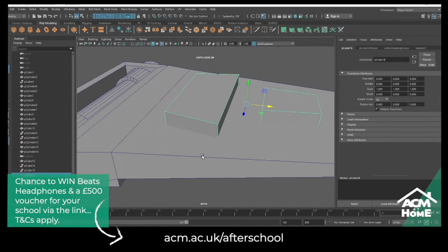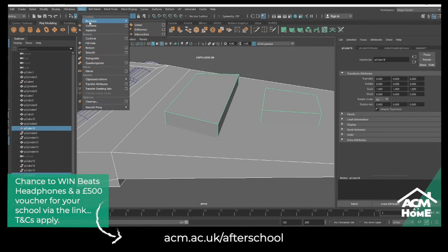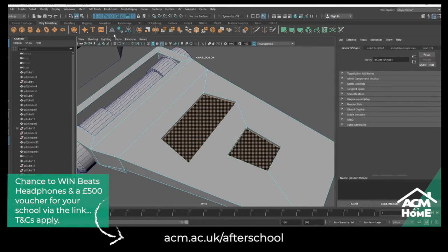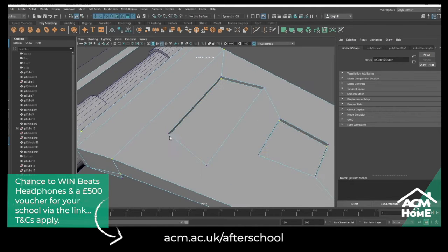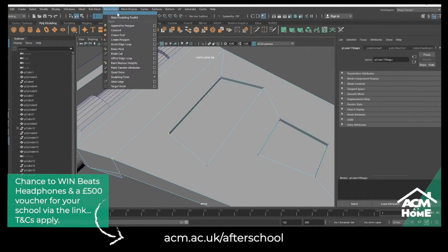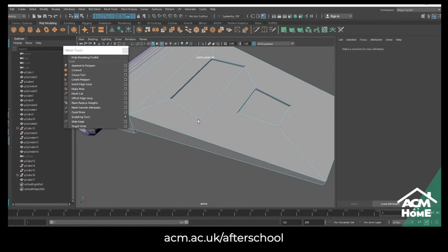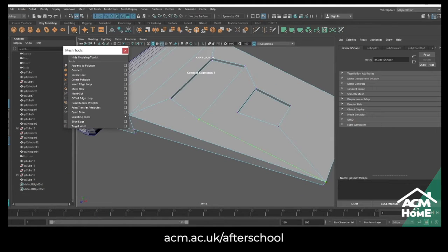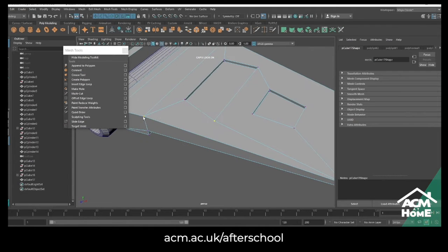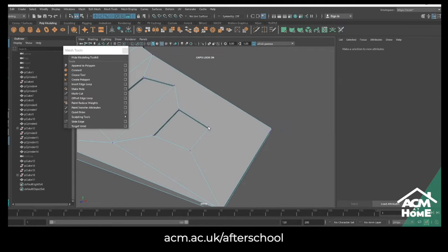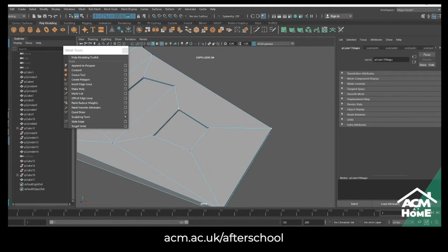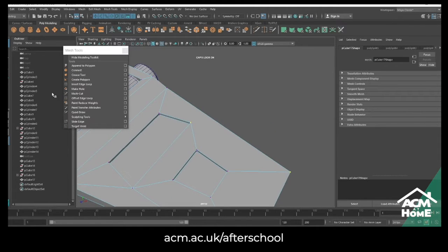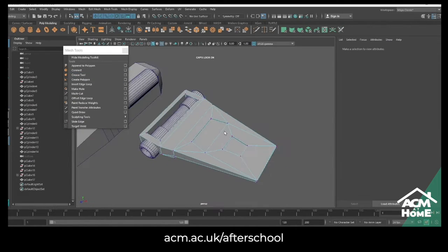And from there, combine the two, make sure to delete history, just so there's no craziness happening in Maya. And then again, run the same Boolean operation that I did before to make sure there's an intersection of the original mesh coming out. And again, cleaning up the areas that need to be a little more technically sound, so Maya doesn't misbehave later on. Because it's one thing to make something look pretty, but if you leave it technically flawed, it does throw hiccups every now and again.